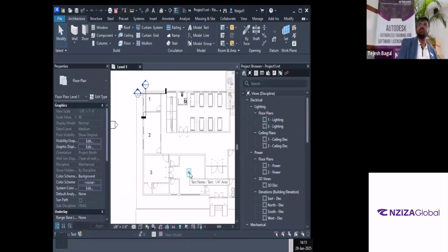All right. So this is something that will happen when you work on a Revit project regularly, that the architect keeps on updating their model. And we need to make sure that we are using the latest architectural model. So for doing that, there is a system in the links. All the links that we have brought into our project, we can reload those links.